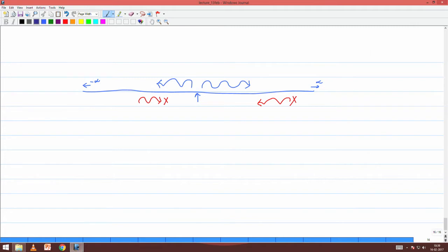But then what you will see is that just these two travelling waves will not be able to satisfy the boundary conditions associated with this point. What are the boundary conditions? There is a jump in shear force of the beam, and that jump in shear force has to account for this excitation force. The discontinuity in the shear force diagram is essentially equal to the applied force, right. Because you have an applied force, there is a jump in shear force. But there is no jump in the bending moment because there is no applied moment.